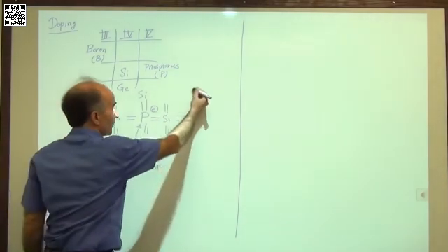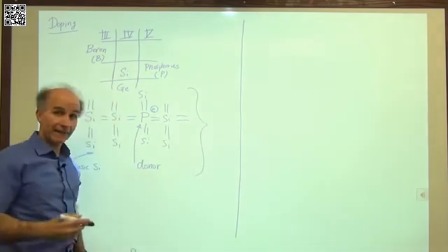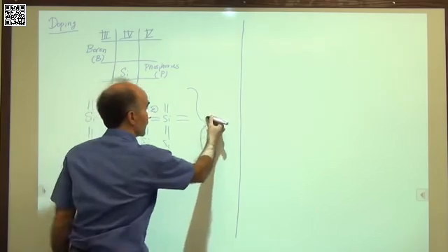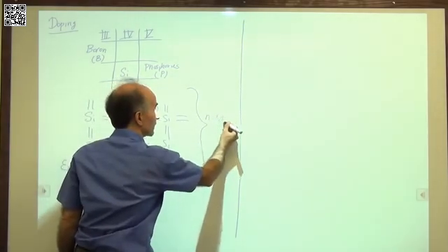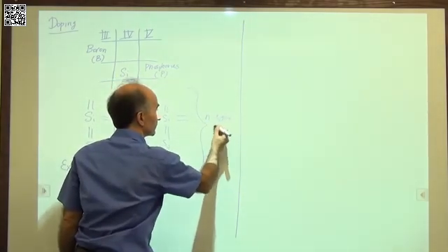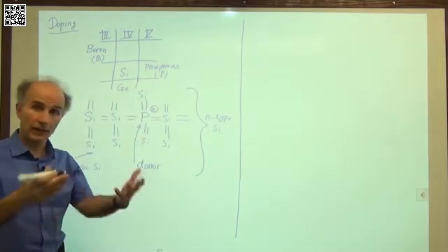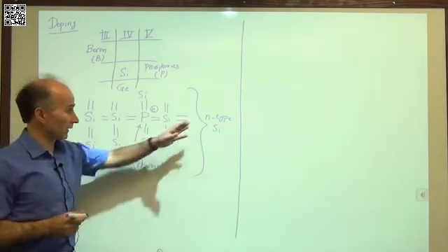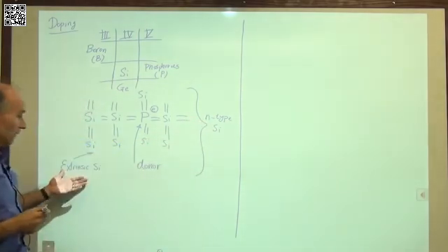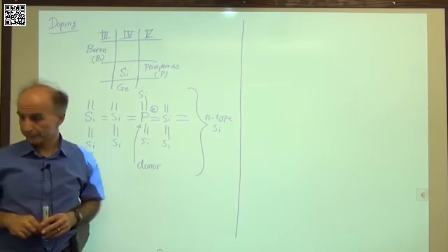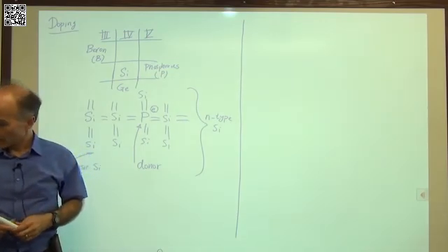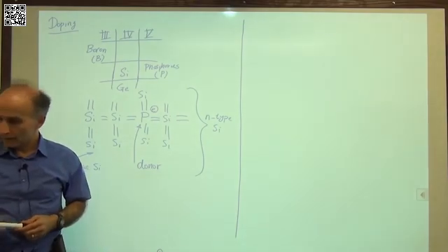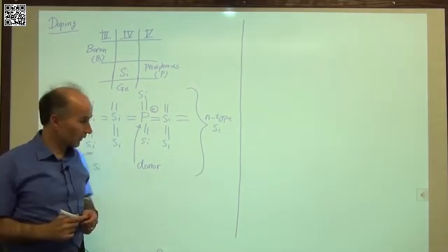And now this overall piece of silicon that has extra electrons for conduction will have a new name. This is what we call an N-type silicon, because it has electrons, more free electrons than pure silicon. And we call it n-type silicon, or we call it extrinsic silicon, and so forth. All right. Okay, so this tells us that we have a situation like this.